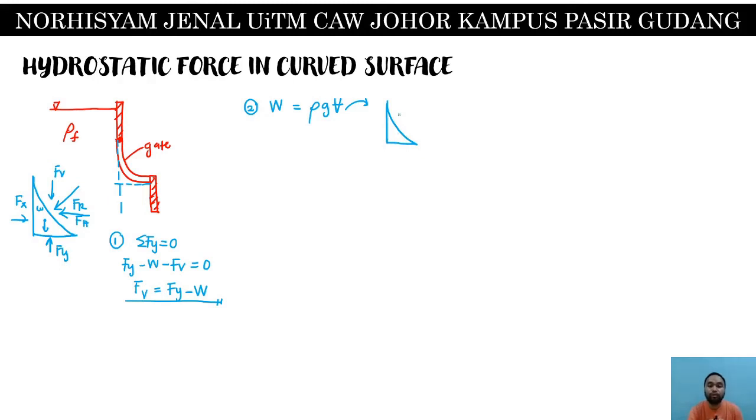We can never use pi r square over 4 again. So how do we calculate this volume? It is calculated through this idea. Assuming we have a square, which is r and r, the area should be r square, radius square, minus a quarter circle that looks like this, okay, where this is r and this is r, and the quarter circle is pi r square over 4. These two will create this volume that we see over here, meaning this part is r, this part is also r. So actually this volume comes from a square minus a quarter circle, then you will get this shape. Okay, so to find out the volume, V is equal to r square minus pi r square over 4 multiplied by the width or the length of the study.